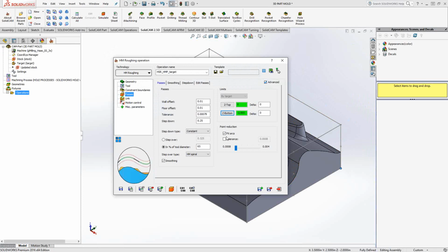Okay. Point reduction, again, speaks back to the refining of the surface, or refining of the toolpath, to make sure that we don't have any weird linear motions. We can probably fit an arc across those linear motions. If I toggle this on and off, you'll see what that does. And again, there's a tolerance along those points as well. A surface inside of software like SolidWorks is essentially just a series of points, and by fitting a better point reduction, we could probably smooth out those surfaces better.